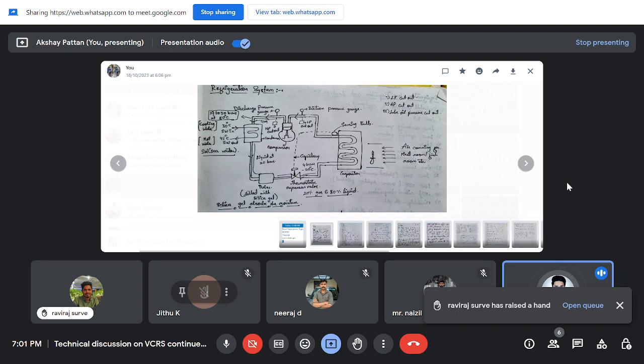The pressure gauge at the discharge side and the pressure gauge at the suction side. Do those come under safety devices or not? These are not safety devices, because they only show the pressure but do not cut out the compressor. Correct. Those do not come under safety devices because they only show the pressure at the suction side and at the discharge side. They do not help in cutting in and cutting out. They just indicate the pressure. So that does not come